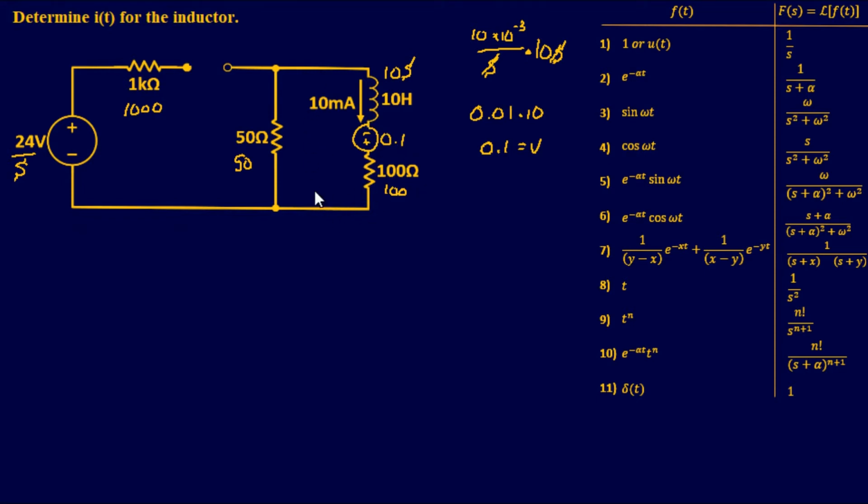So this one's going to be easy on me when actually making my equation. All right, so going back to our circuit, right off the bat, we can go ahead and take this guy off the list and this guy because there is no current going through either one of those. So right here, we're going to make an equation for this loop right here.